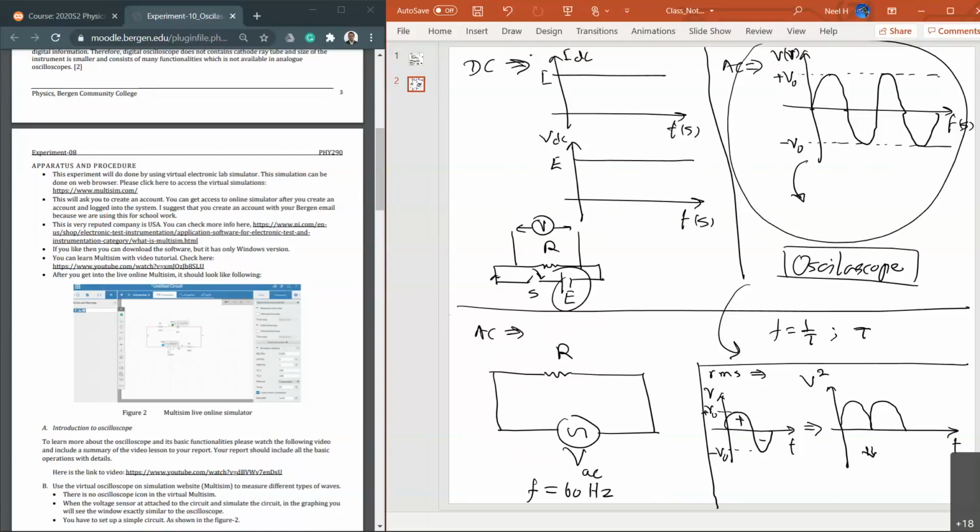So you take the square root of that, and that is called the VRMS. So you square first and everything becomes positive. Then you take the square root, which is a little bit lower now than the maximum possible value.